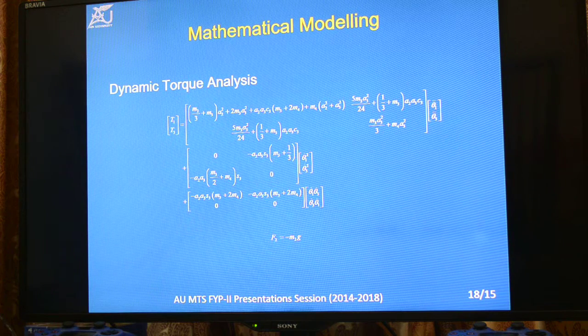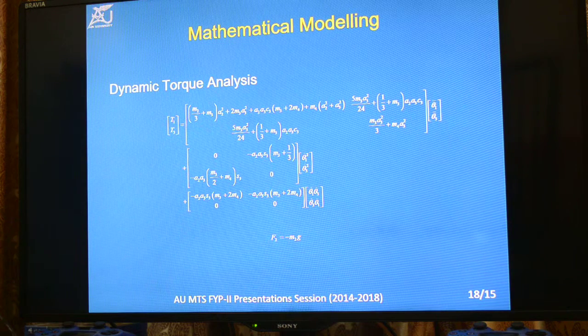I have divided it into two categories. As you can see, and as I discussed in the first slide, x and y are not dependent on z and z is not dependent on x and y. So the prismatic force, that is F2, is independent of any torques, and it's actually dependent on the torques, but the thing is the M2 I use is from the MATLAB simulation. It contains all the masses acting throughout the robotic manipulator, and it's like 7.2 kg for the whole arm extended. And it can be simulated in MATLAB or in a 3D virtual environment.